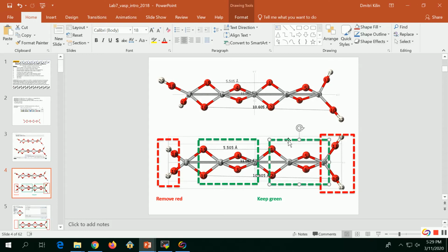For all the molecules? We should get to practical aspects very soon, but since we started, if you want to use the software that we are starting to learn for molecules or quantum dots or isolated objects without periodicity, then one will need to add an amount of vacuum that substantially exceeds bond length, like 10 angstrom on X, Y, and Z. Okay?